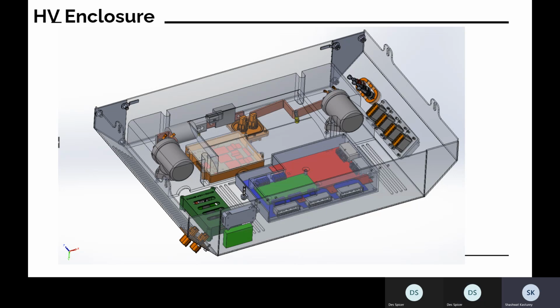The cells themselves don't shut off if they're drawing too much power or if the voltage gets too low. If you short a cell to itself, it'll catch fire and explode. So it's a controlled thing. We set a floor voltage, basically, when we're programming the AMS, and if any cell hits that at any point, the car shuts down.